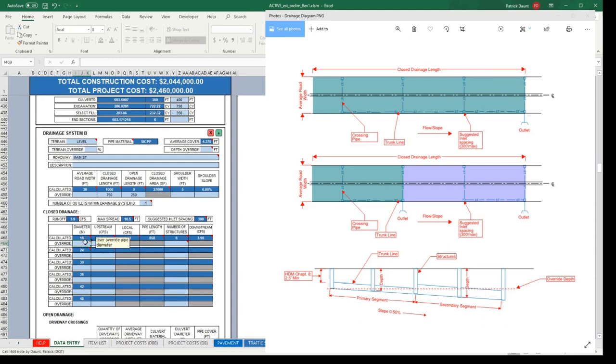So for this preliminary phase, since we really don't have any good handle on existing flows, you haven't done any kind of drainage watershed work on it, we haven't delineated any watersheds, we're just going to assume that we need to automatically upsize to the next size bigger in order to maintain the existing capacity upstream. So let's just manually put in 24 inches.